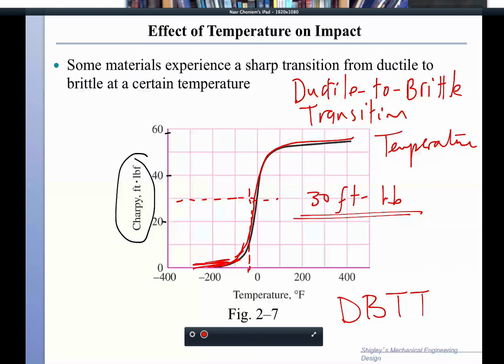So that's what we expect. Now, if I look at the effects of strain rate on the yield strength of the material and the ultimate strength, I would expect that the material kind of stiffens as you hit it harder. So the harder it is, the higher the strain rate, the more the material is going to resist. And that's basically the qualitative aspect that we're looking after right here.